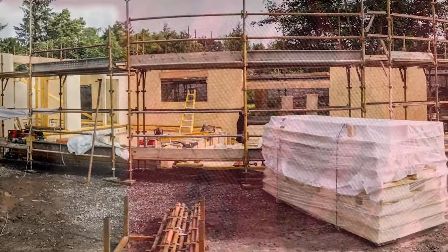My house used Wraptite externally and Reflectitherm Plus on the inside to limit the air leakage as much as possible. This not only assisted with meeting the targets in the building regulations for overall energy performance, but also ensured the mechanical ventilation and heat recovery system were able to operate optimally, ensuring good indoor air quality while minimising space and heating costs. The final part of the building envelope we must address is the roof, and there are several common types of roof and even more factors to consider when designing one.